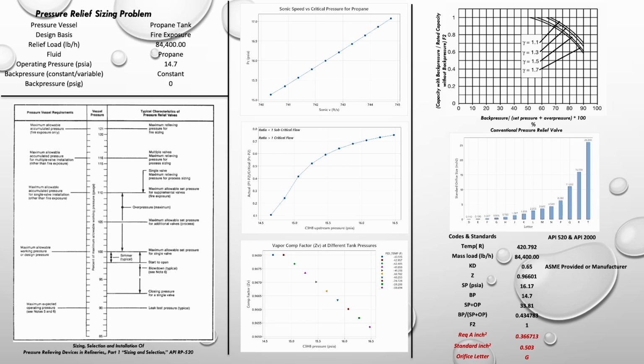Normally, if you want to be sizing an orifice based on your calculation, you can, but I would seriously doubt any manufacturer out there is going to be designing an orifice to a second or third decimal.